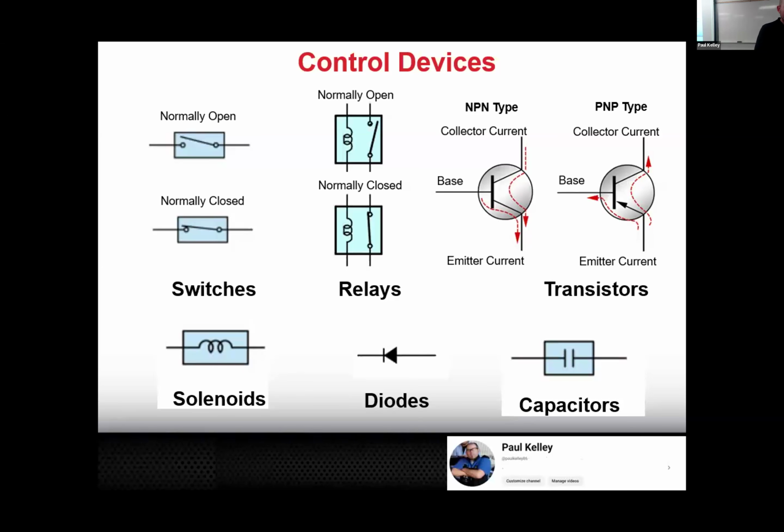And we'll cover some of these a couple times because they can be a little complicated. But for example, a transistor, let's just say we'll go with an NPN type. A transistor is just like a relay, like this, right? We can have the low current side control the high current side. So the computer likes to control the left, and the right does big work, heavy work, high current work. This transistor is what I would like to say is a solid state relay.